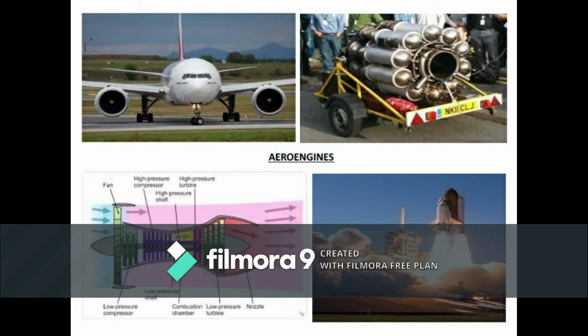That supersonic air creates sufficient compression due to the formation of shock waves, which is mainly responsible for the high pressure rise in the air intake. That high pressure air is taken to the combustion chamber, fuel is directly burned, and it is expanded in the nozzle, and thereby we can produce tremendous amount of thrust.